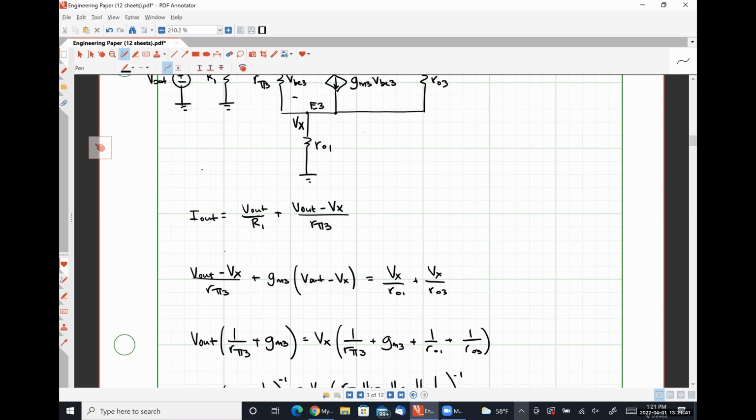Being able to look at a portion of a circuit and say, oh, that's a current source, or that's a cascoded current source, or that's a current source generated by a resistor, and then knowing how that works without having to derive everything from scratch every time. Because if you have to derive everything from scratch every time, every problem's an hour-long problem.